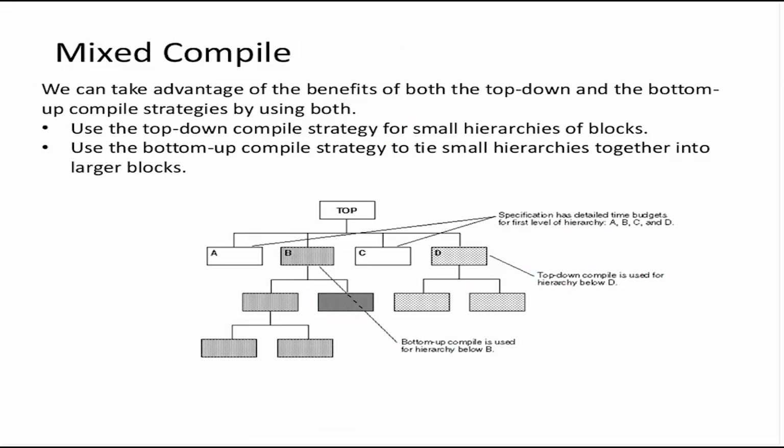Top down is much better in terms of area and timing optimization if the design is not too large. So in fact we do chip level like this. Let's say our chip has multiple blocks. Let's say one is USB, another a CPU, and a third block can be an MPEG decoder. A USB, a CPU and an MPEG decoder individually are very big blocks. We cannot synthesize this from top down. What we do is we synthesize USB separately, we synthesize CPU separately, we synthesize the MPEG decoder separately, and then we do top level synthesis.